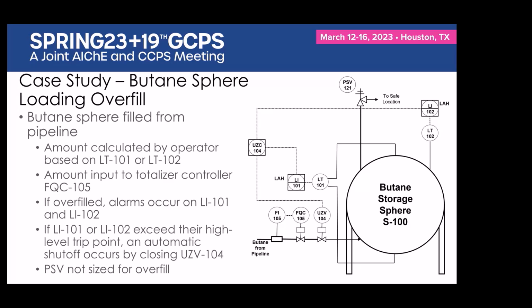And furthermore, when you showed that your target maximum event likelihood was achieved, you have effectively proven that whatever performance you're getting out of the safety instrumented function that's already there in your fault tree, by definition, has to be adequate to achieve tolerable risk.